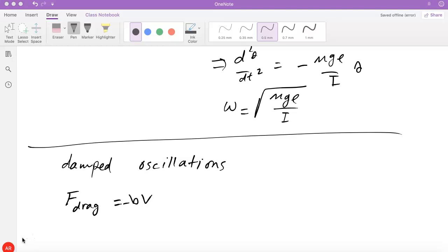I think the linear drag that we're focusing on here is known as the laminar drag. So it's like the fluid you're moving into moves in smooth layers, and that gives rise to the linear behavior. You may have quadratic behavior, the turbulent type of motion where you really mess up the liquid or gas around you as you move, and then your dependence on speed is even stronger. It goes as velocity squared. But we're going to focus on this particular model of a resistance force to motion that's linear with the speed.